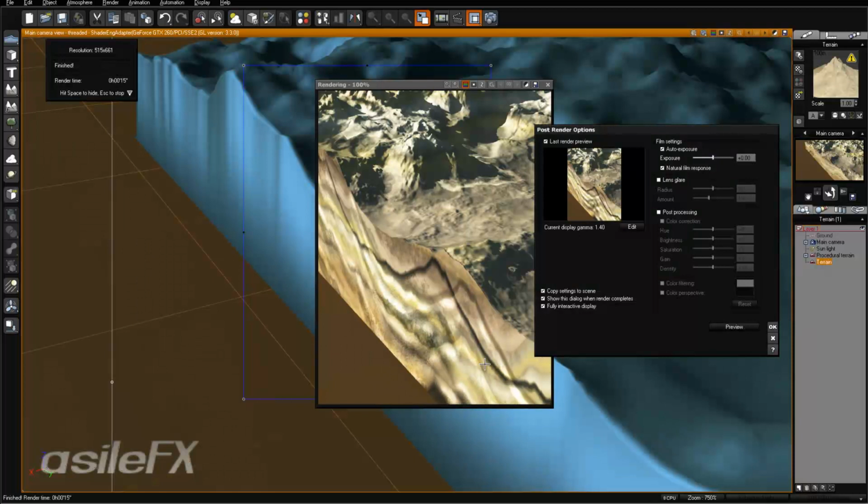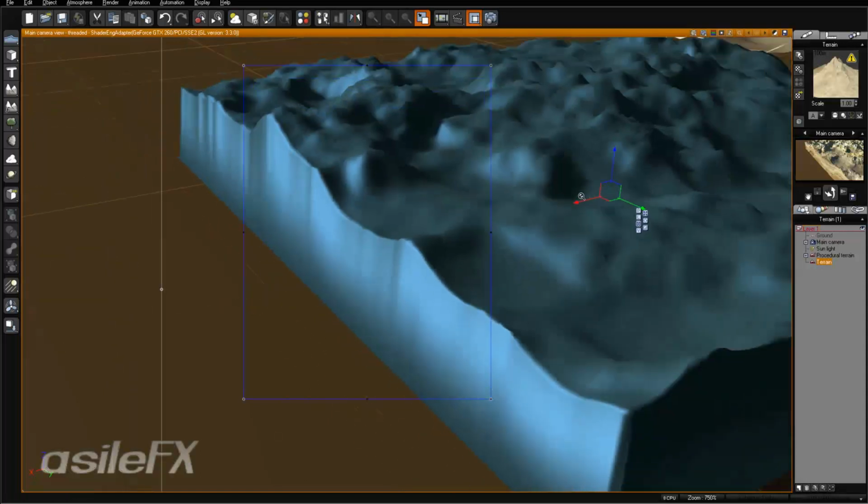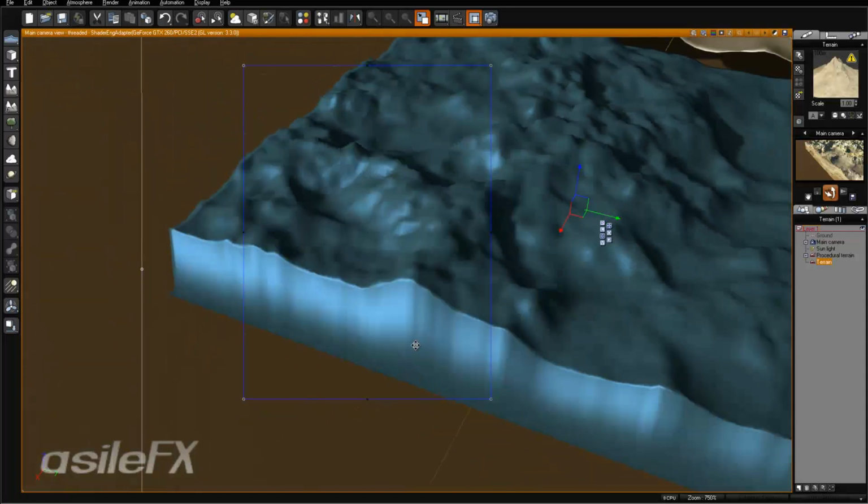May need to rotate that around. It does not look like it is lined up entirely. It might be because of the offset I have set up. But for the most part, it is conforming to the terrain. So if you have a standard terrain, you can just export that image and use that as the altitude. If you want to convert from a procedural to a standard, same thing, just making sure that you export out that image.